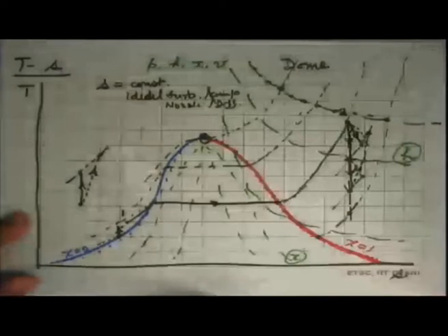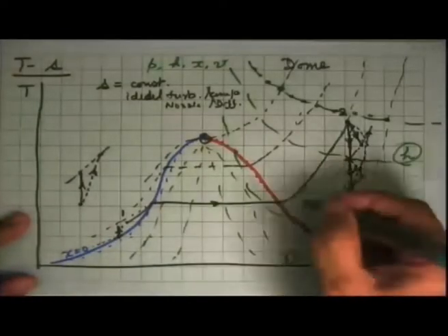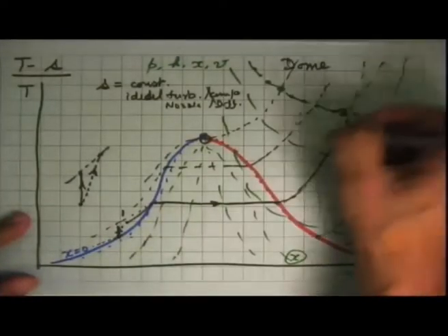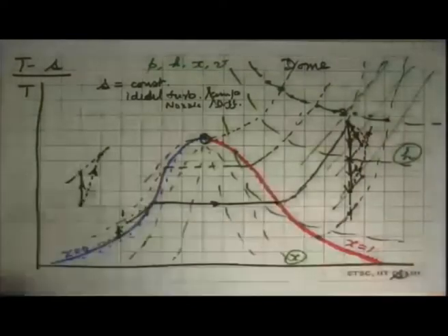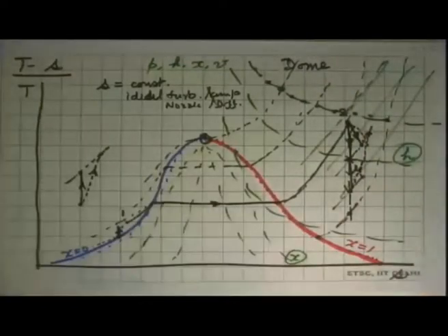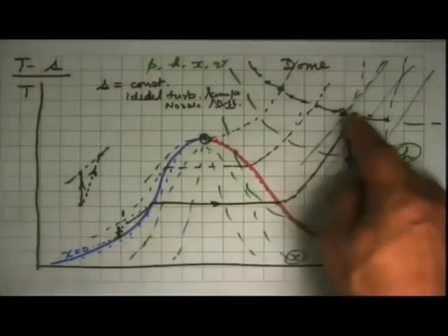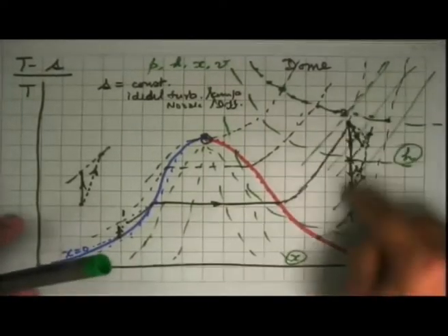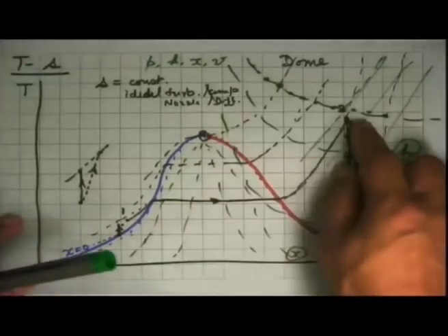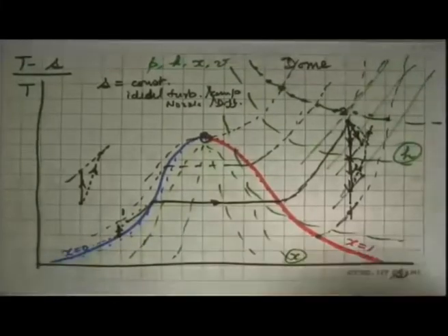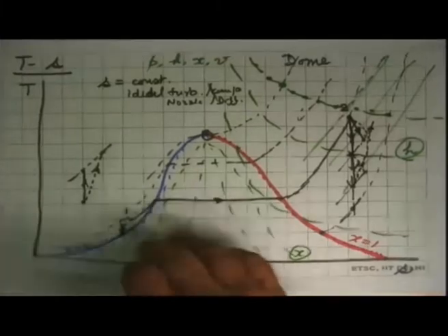So these are constant enthalpy lines. Specific volume lines are also somewhat similar on this, but of a different slope. So that tells us everything that we wanted about the TS diagram. And I have illustrated this with a heating process, which is like a cooling process, the turbine and a nozzle, and also the throttling process on this diagram. Okay, now we will see the real TS diagram.